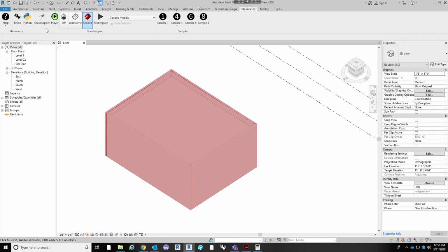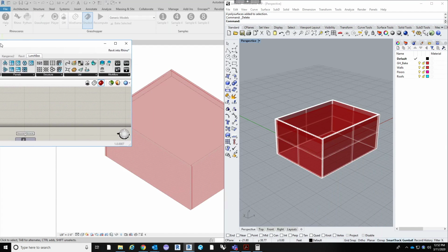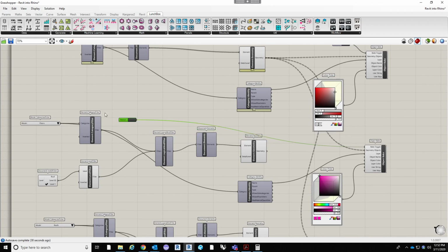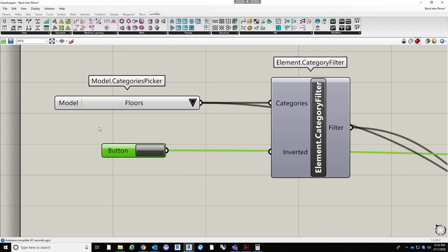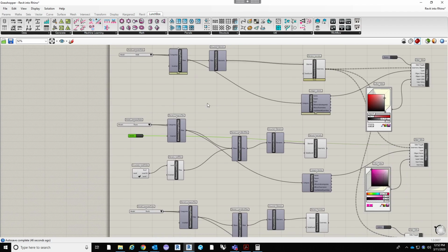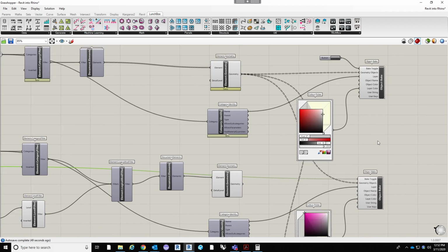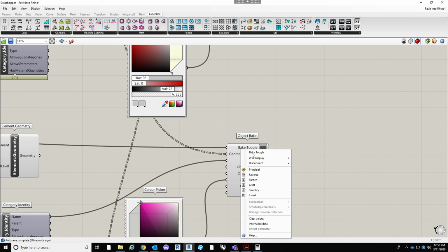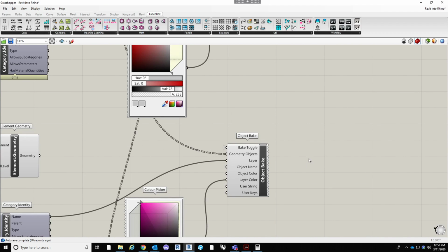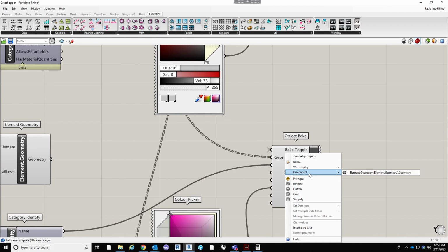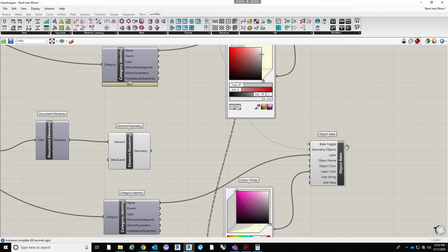One thing I wanted to show you guys that I found out. In Grasshopper, obviously we have a lot of different wires. We want as much organization within the Grasshopper script as possible. And so one thing we can do if we wanted to drag stuff off is, if you right click on the input, you can change the display of the wires.